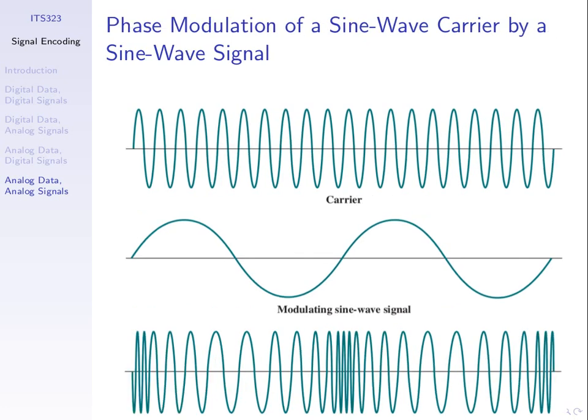And the one before that was phase modulation, which turns out looks the same as frequency modulation, because when you look at varying the phase, here we see we start, we go down, and we have a different phase. As we change the phase continuously, we get the same effect of changing the frequency. So the two common ones are AM and FM, amplitude and frequency modulation.